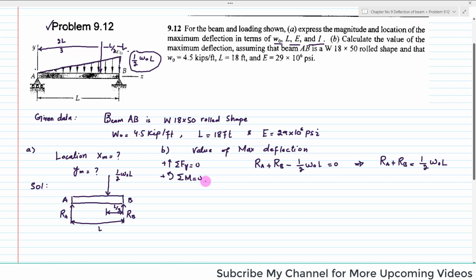Clear? Now we will use the second equation, the sum of all moments about any point is equal to 0. So we will take point B. The sum of all moments about point B is equal to 0 and counterclockwise is positive. You can see that the moment about point B due to the force RA is RA into the perpendicular distance L. So RA into L, and as it is producing clockwise rotation about point B, it will be minus. Clear?